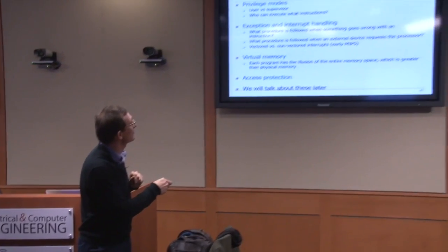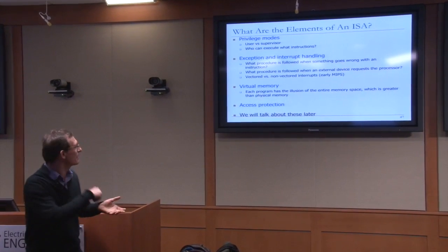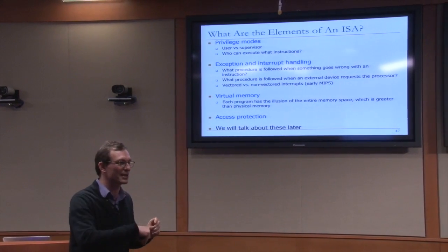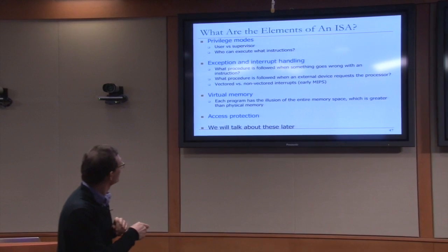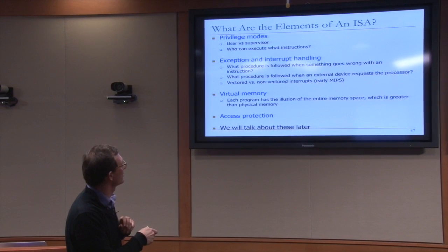What procedure is followed when an external device requests the processor? That's the interrupt. And we'll distinguish between interrupts and exceptions. Interrupts are external to the executing program. Exceptions are internal to the executing program. Vectored versus non-vectored interrupts, again, we're going to talk about this also.